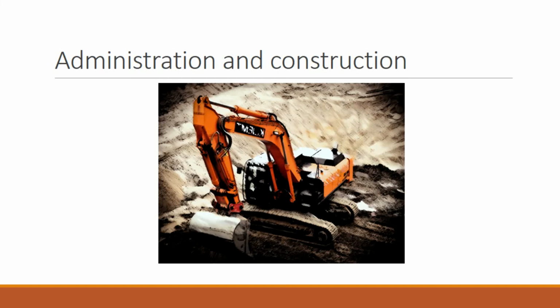And finally, we have to start the overall work process. Equipment and systems must be put into operation at the start of commissioning or earlier, and perhaps this stage should be classified in the next phase, which is stage 4. Prior to energizing the system or performing a full startup, other regulation and adjustments must be made as well. Before fully operating the equipment and starting other aspects of commissioning, this could involve factory representative startup, calibration, and other considerations.